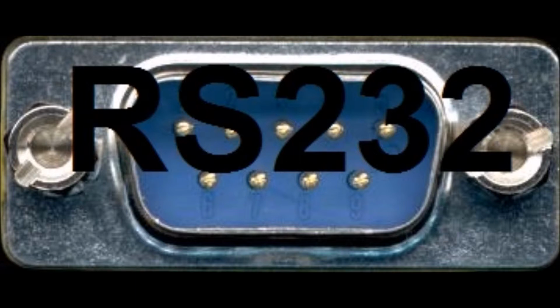The idle state, mark, has a signal level negative with respect to common, and the active state, space, has a signal level positive with respect to common. The RS232 interface presupposes a common ground between the DTE, data terminal equipment, such as a computer, and the DCE, data communication equipment, such as a modem or microcontroller. This is a reasonable assumption when a short cable connects the DTE to the DCE, but with a longer line or connection, devices that may be on different electrical buses with different grounds, this may not be true.